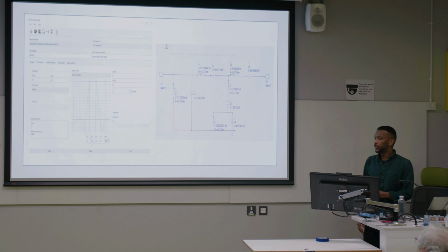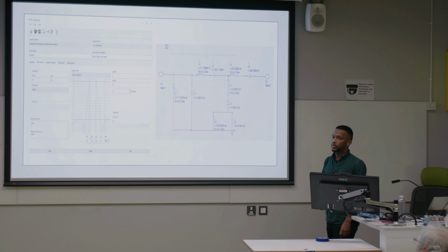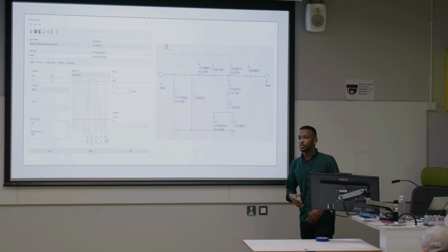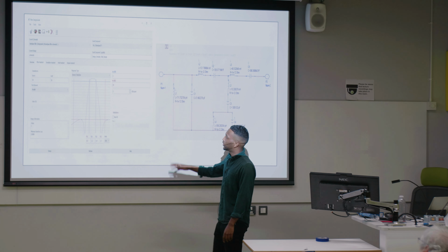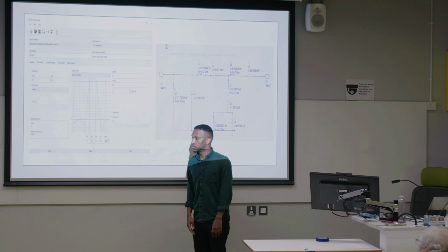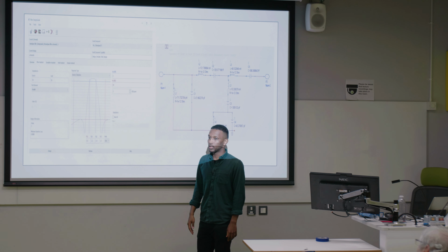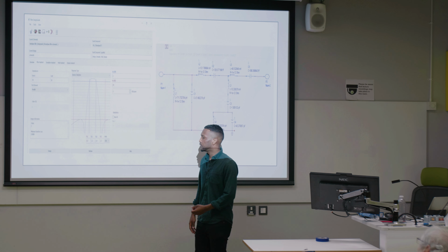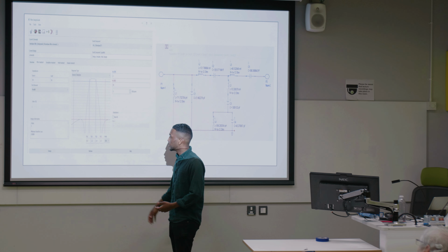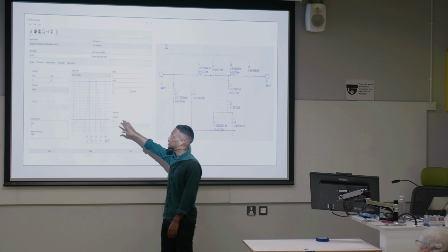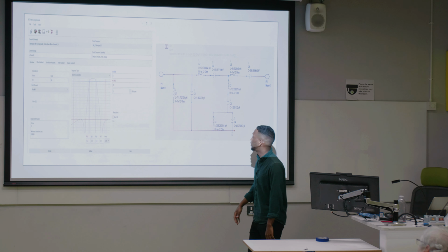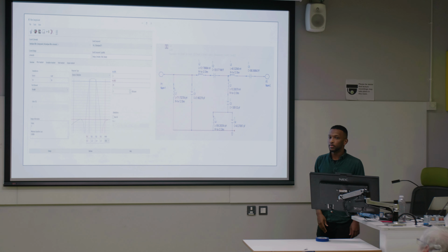So the whole point of doing this test is to actually build a bandpass filter to remove all the harmonics, the signals that we don't want, and the noise. Here we've used ADS, the design guide on ADS. It makes it very easy for us to design a bandpass filter. All we need to do is put down the specifications we need for our bandpass filter, and boom, it gives us all the components.